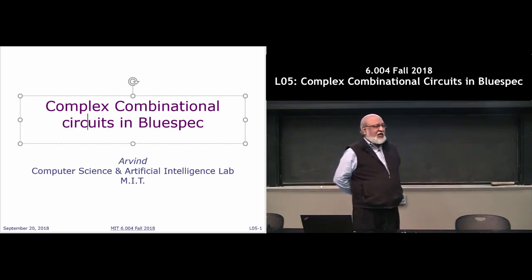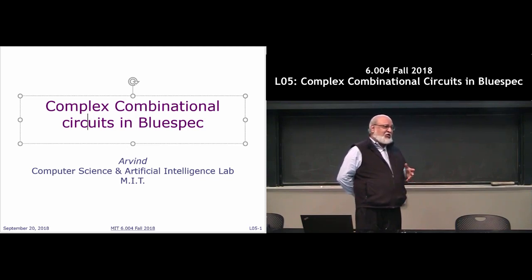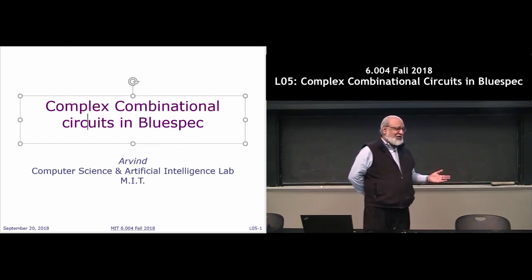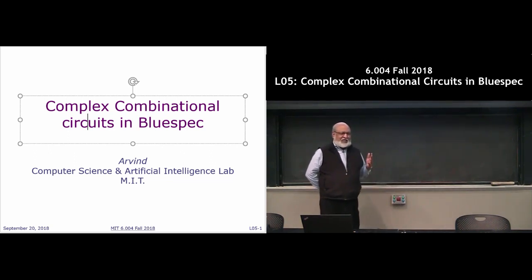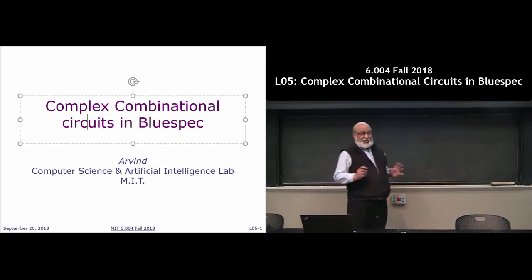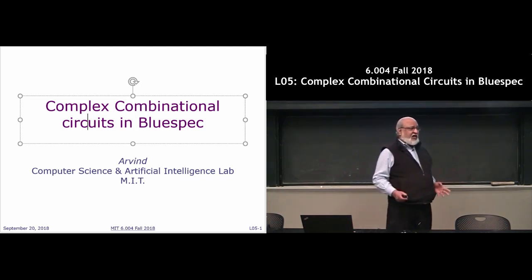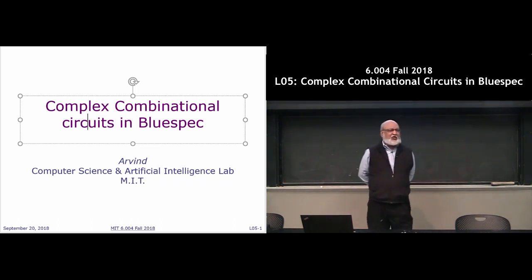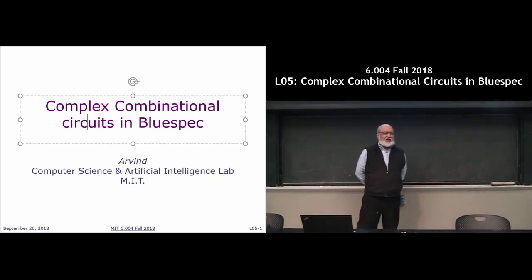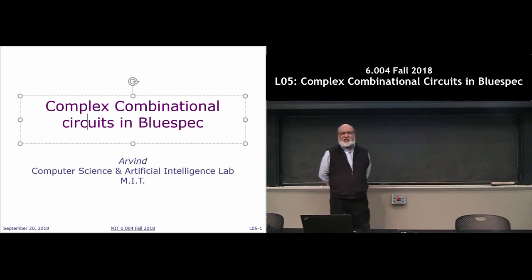The compiler convention is such that you may have no clue which wire it's referring to. Even though the compiler has a systematic way of doing this, that doesn't mean the naming convention matches our intuition. So whenever you do this elaboration, sometimes it's very, very hard even to find inputs and outputs. Internal wires, no chance, because there'll be optimizations. If you're looking for CS0, it may be very hard to find it in the circuit.